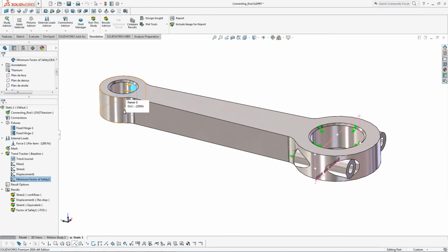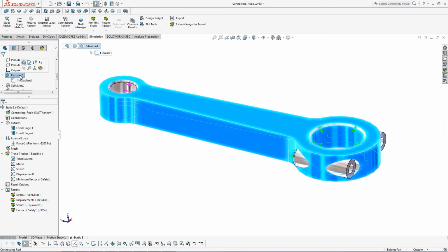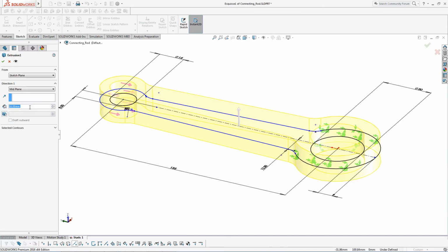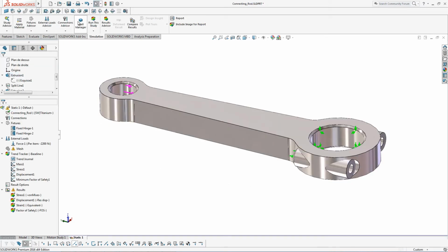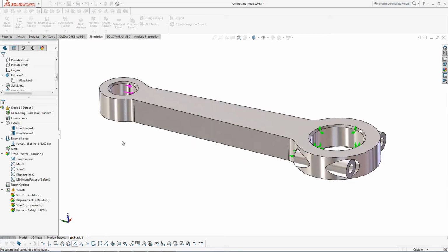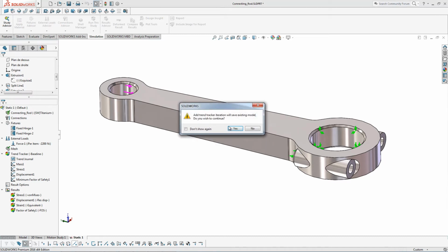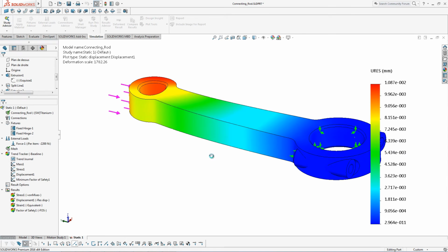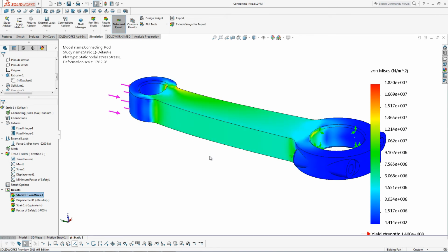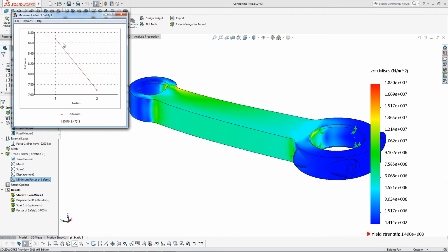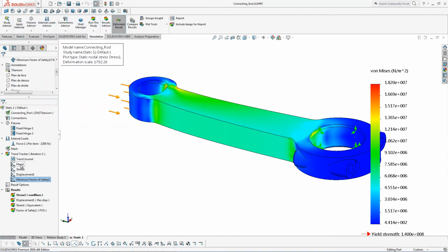All right, now let's say I want to make a change to my baseline, right? Let's start by just changing the thickness of that extrusion. It's 16 millimeters now. Let me turn it down to 14 and rerun this. Now, if you're making these kind of changes, that's one that you could do with the design optimization pretty quickly. But I'm going to go ahead and add those values. And we can see exactly what that looks like, right? How's my factor of safety changing? How is my mass changing? How's displacement changing? I've got access to all of those.